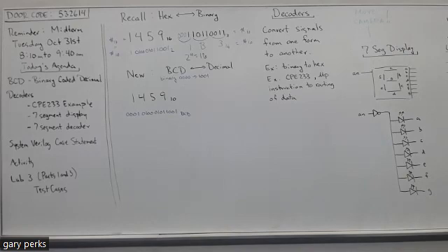And then on the output side of the decoder, there's ALU fun, ALU source A, ALU source B, PC source, RFWR select. Now you're going to learn all about what those things mean when you take the class. But what I want to point out at this point is, look at where those outputs of the decoder are going to, like where they're connecting. Like where else do you see ALU fun? In the diagram, you look. Yeah, it's by this thing called an ALU.